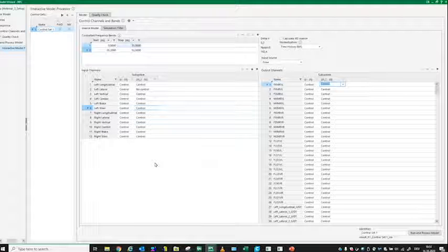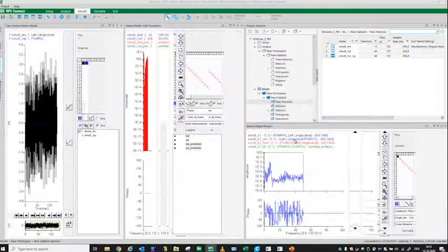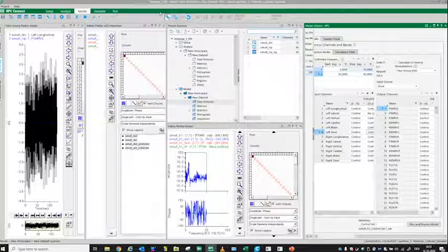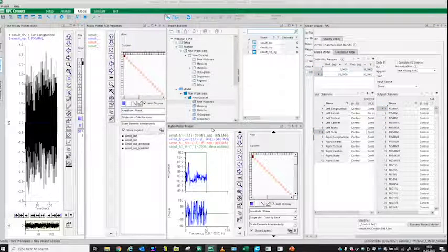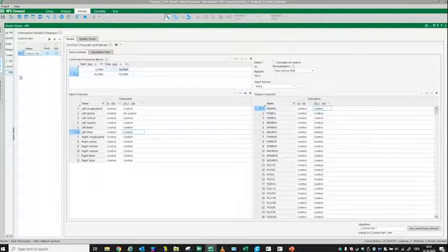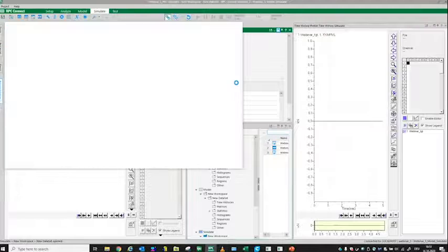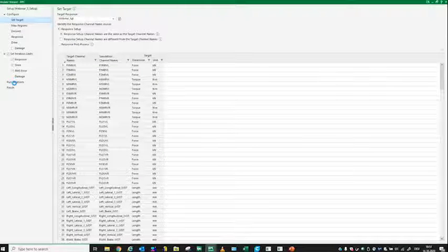Any other questions? Yeah, a couple of others that I can see. Does RPC Connect keep a record of the iteration gains? If they were to go back at a later date, would they be able to see what gain scheme was used for each channel? Yeah, of course. If I have the scheduled iterations, which I showed you a second ago, I'm going back to simulate to show what I'm talking about here. The gain scheduling is kept for each project. So if you save this one here and open a new project, let's go to the run iteration node.